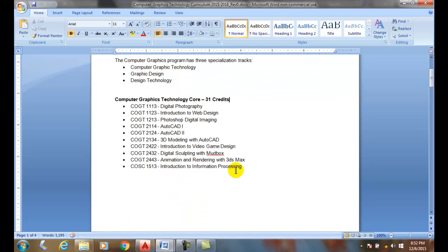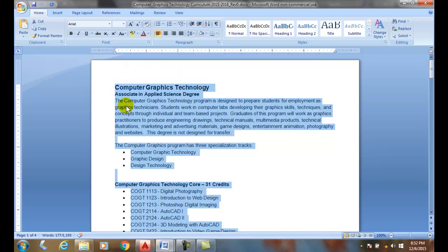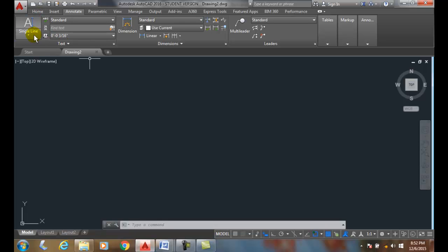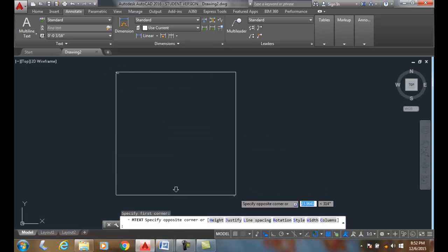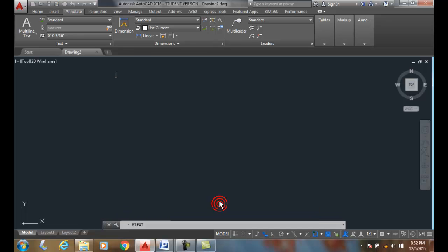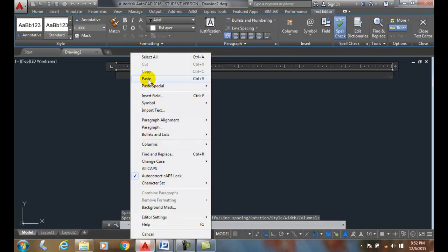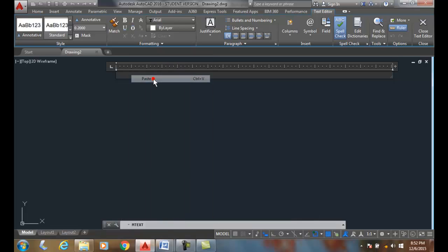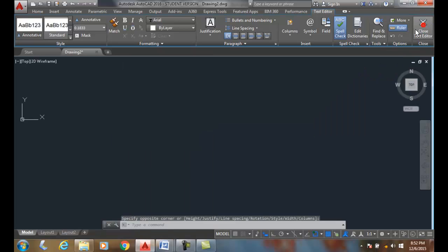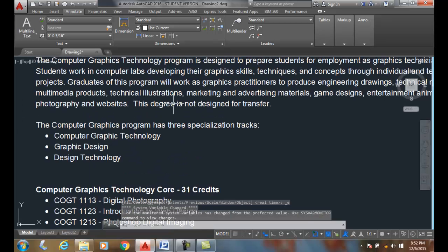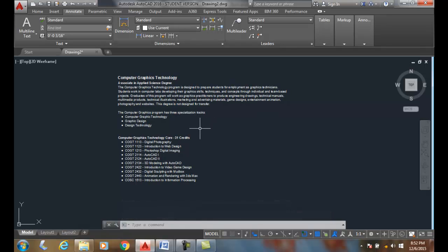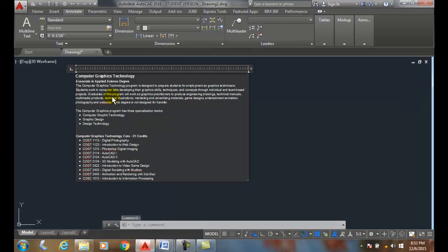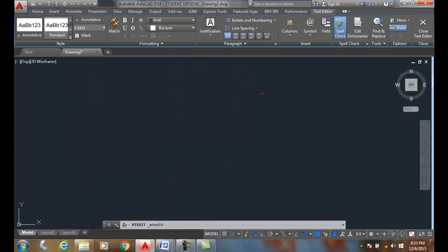For example, I'll come into this Word document and I will right-click and I'll say copy. Then I'll go into my AutoCAD drawing and I'm going to go into my multi-line text, then I'll right-click, and I could just say paste if I wanted to, and I'll do that. Boom, and then I can close the text editor and double-click Zoom Extents, and there is just a straight-up paste. It's a regular text object, right? It's no different than any other text object that we have in AutoCAD.